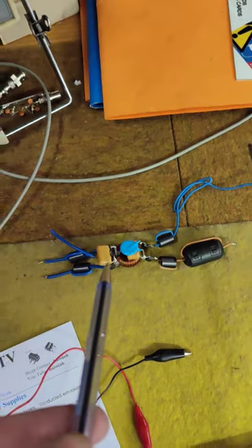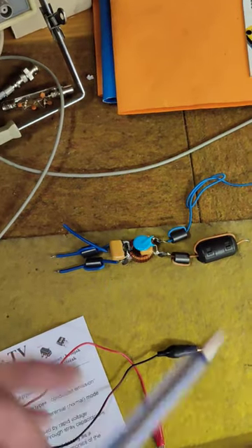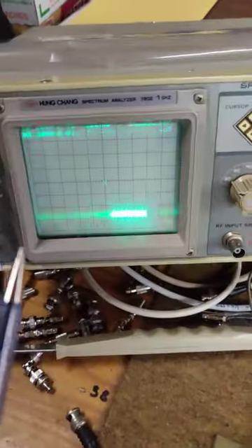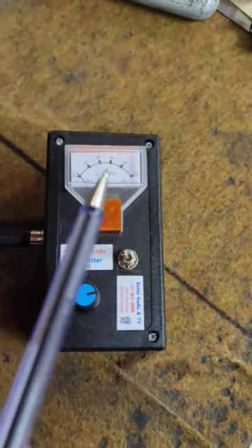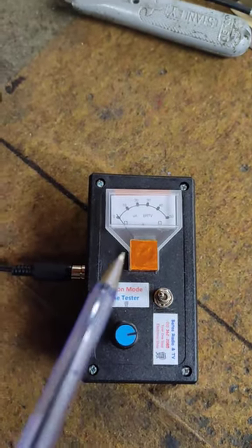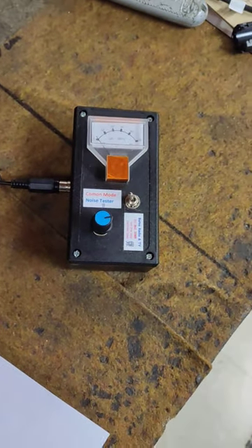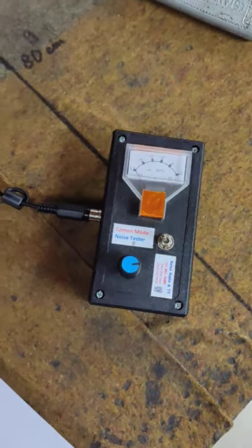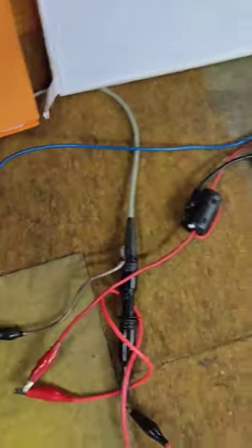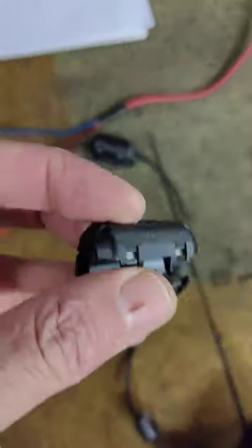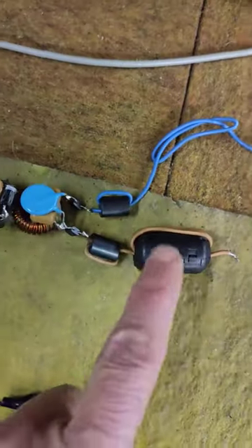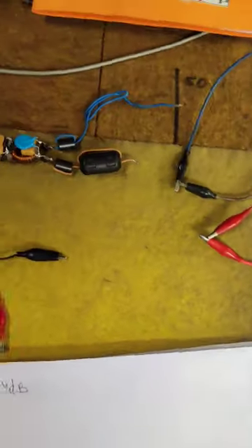That's just one of the filters. As I said, I'm not going to use different types. I'll just use this specific one. And you will actually see that we reduce the noise. Besides on the spectrum analyzer, you'll also see it on the little instrument that we made, that yes, noise has been reduced. And of course, by positioning different ferrite beads, toroids, for clamping on the wires and things like that, like over here. You can't just clamp it anywhere.